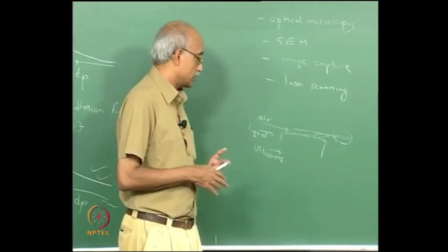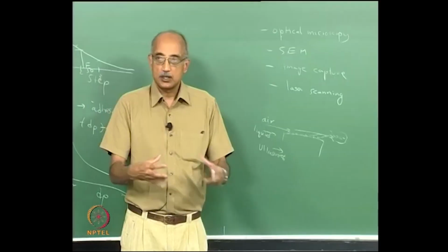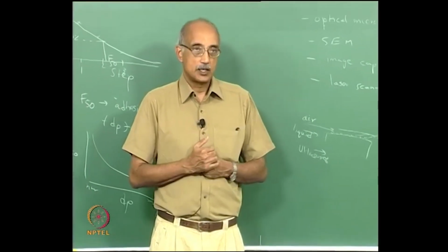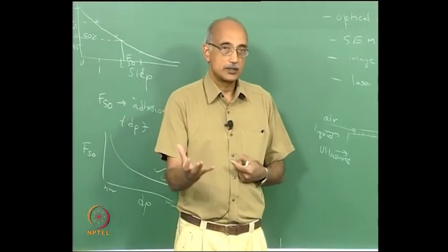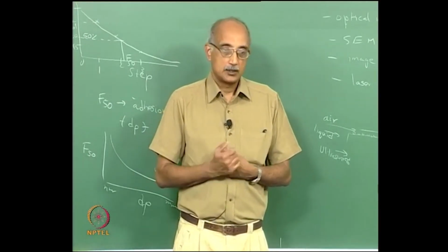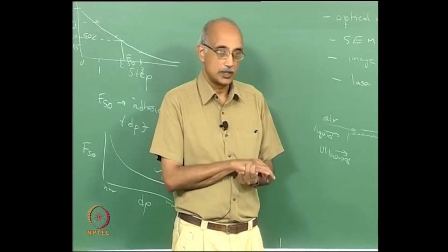So here again, essentially the way you would do this is take the surface, immerse it in an ultrasonic medium, remove particles from it by turning on the ultrasonics, and then look at particles that have become entrained in the liquid, and that gives you a measure of how strongly they were adhered to the surface to begin with.